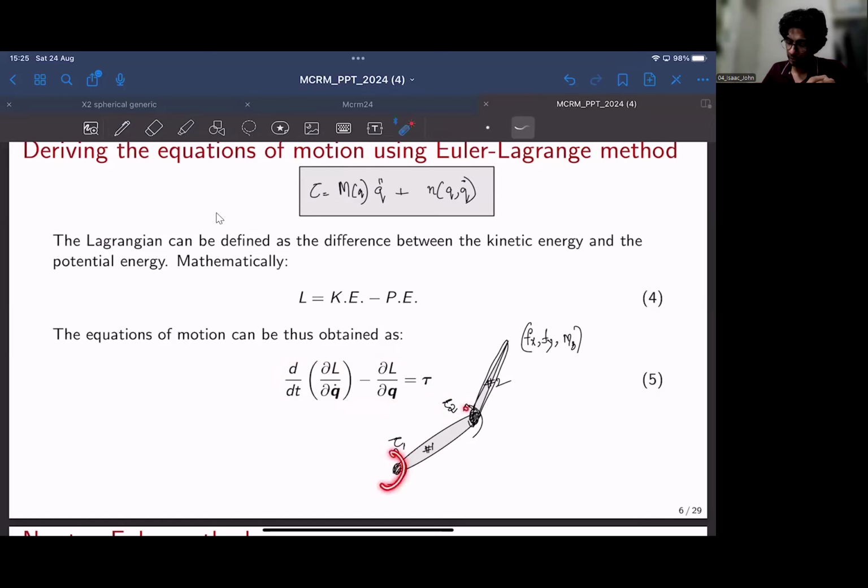See, the torque supplied is always along an axis that is along the revolute joints. Right? If this is Z1 and Z2, these torques are always directed along this axis of the revolute joints or axis of the motors. But for a lot of other purposes, maybe for design purposes or for testing the design and its safety, plenty of times we may need to estimate the other components of forces.